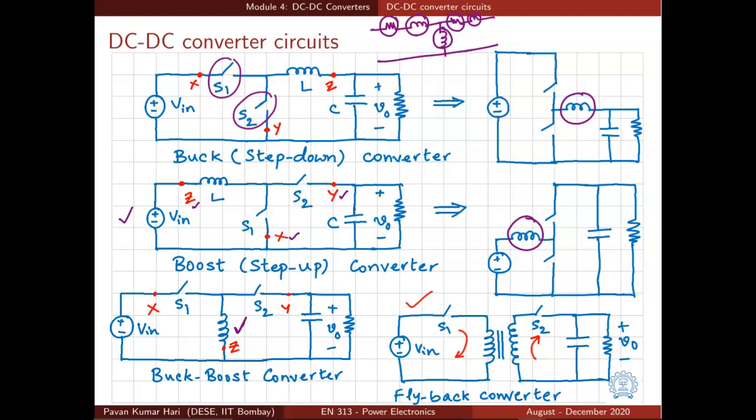So we have to go back to the performance metrics of a power converter that we have discussed, and we look at different metrics. We can look at the cleanness of waveforms, how clean they are, or we can look at the size of the magnetic components, whether we need a smaller inductor for one power electronic converter or not, or we can look at the EMI, the electromagnetic interference, or we can look at the regulation, which converter gives a tighter regulation of the output voltage, and then sensitivity to disturbances.